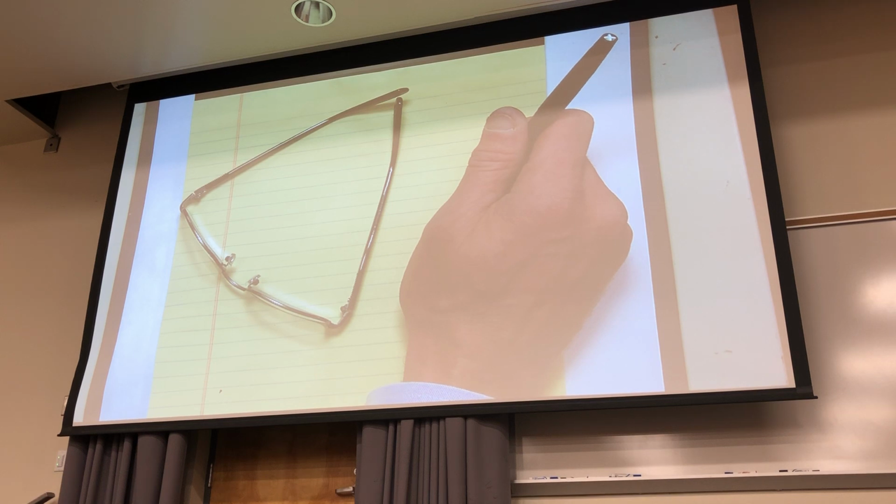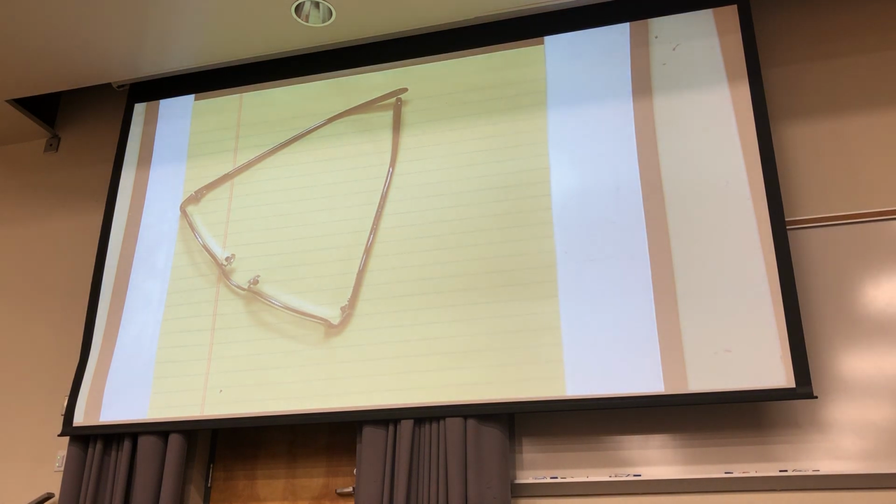Then after that, we did the DTFT. Does everybody recall that? The DTFT is basically the Fourier transform, only there's one major difference. Now we're sampling the signal, and because of that, we repeat the DTFT signature waveform over and over again, every 2 pi. This is important. So now by sampling, it causes the entire axis to be populated with information that just repeats. But all the information you need really is between minus pi and pi in the capital omega domain.